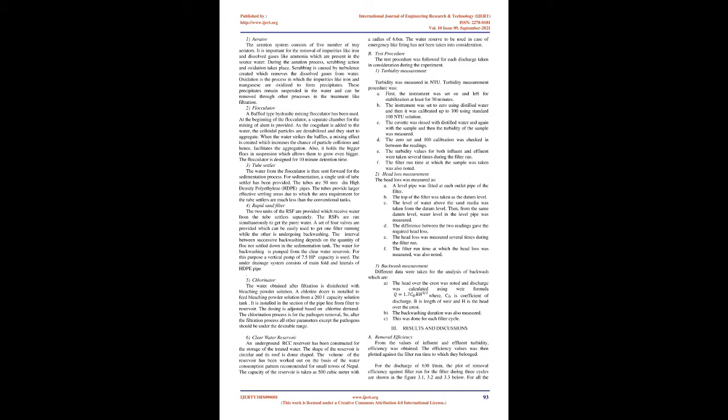During the course of filtration, more and more particles get stuck in the filter media, which leads to the clogging of the filter and a decrease in the filtering rate of RSF. So, to re-achieve the previous performance of the filter, cleaning should be done. Cleaning is done by backwashing.